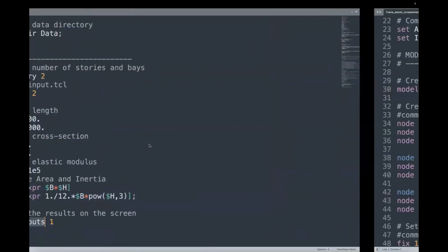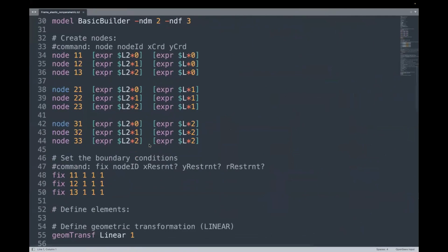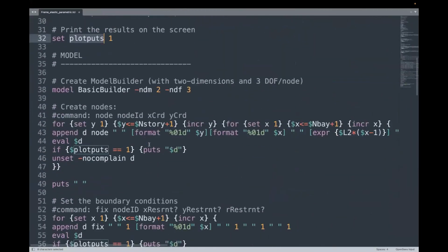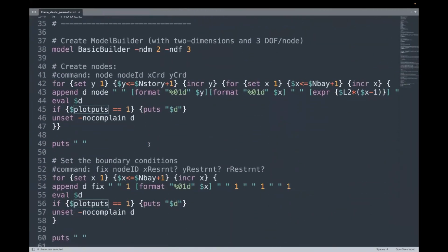After this, if we continue the code by adopting a non-parametric version, you can see what we are doing is to fix 1, 1, fix 1, 2, fix 1, 3, basically fixing the 3 nodes. In the parametric version of this code, I think if you can understand this logic, right, I put on line 49 these puts to make an empty line to divide the information between the two. So you can see here that we have basically a fix only considering the first bay.